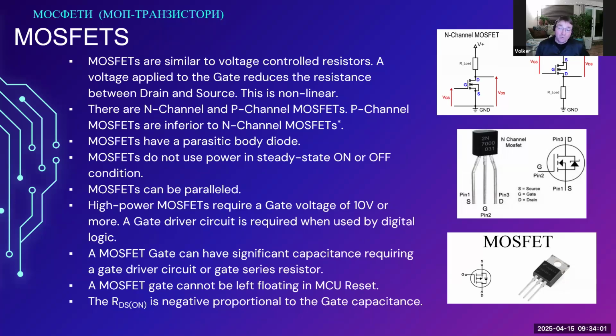They basically use these built-in body diodes of a MOSFET as flyback diodes for the motor. Typically, if you use bipolar junction transistors in a bridge circuit as a motor driver, you need to supply these flyback diodes in addition to the actual switching device.